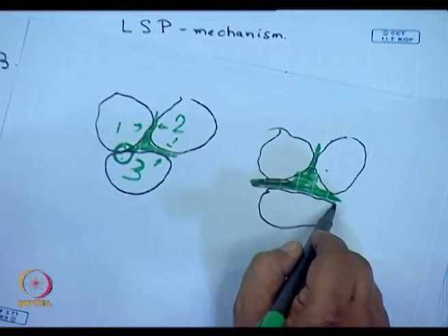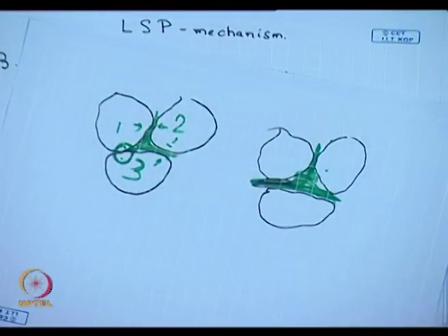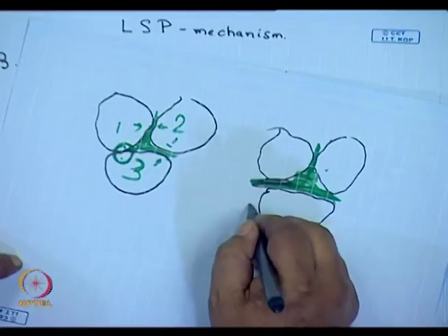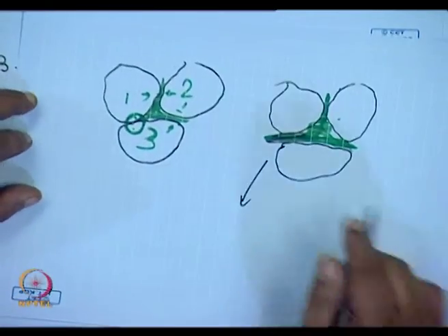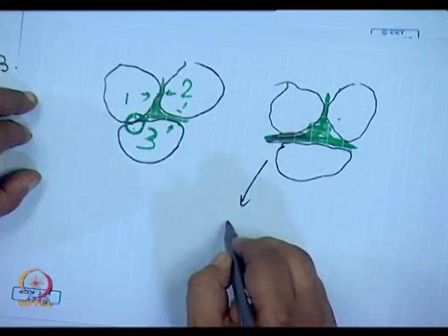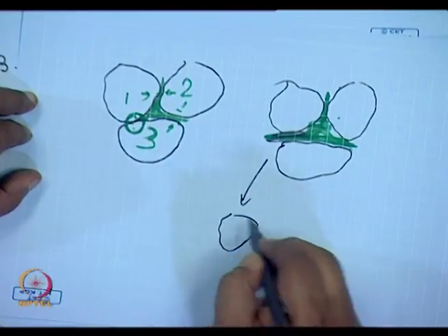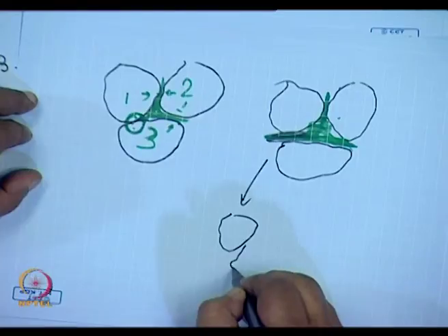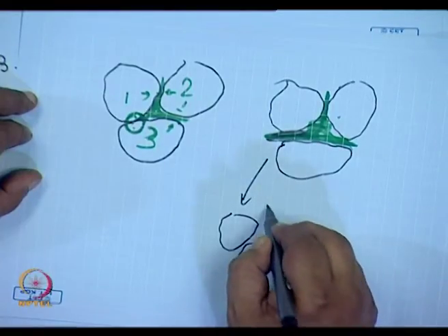At this particular stage, the liquid is doing two things. The liquid has been formed, this sort of a thing has occurred. Due to the capillary pressure, these grains whose surfaces have been rounded off, they are pulled closer together due to the capillary effect.